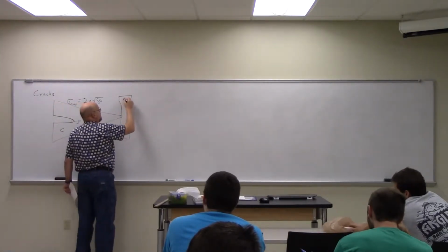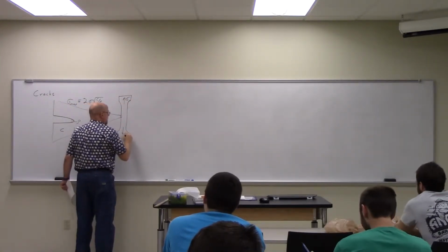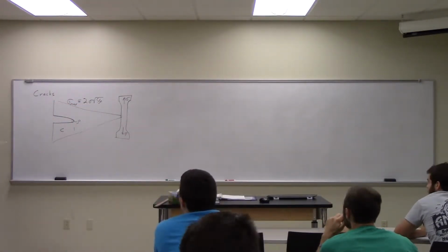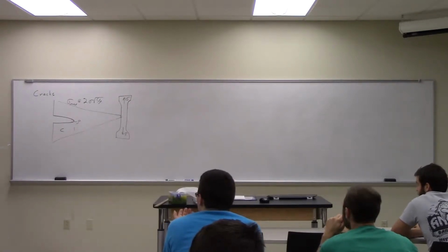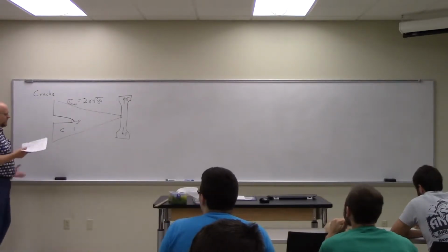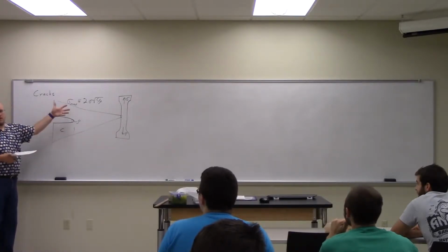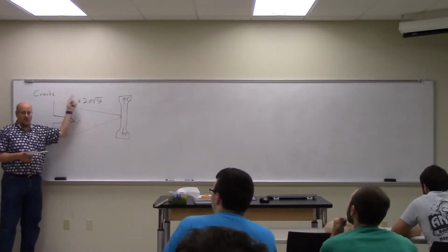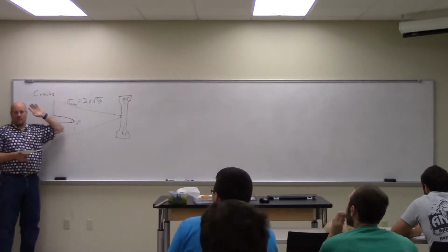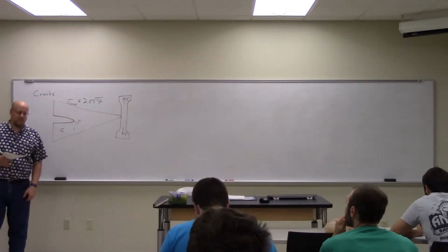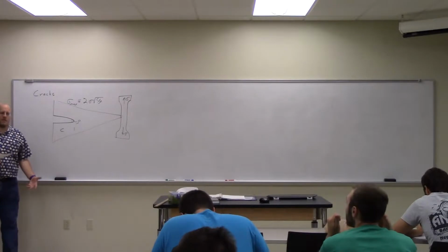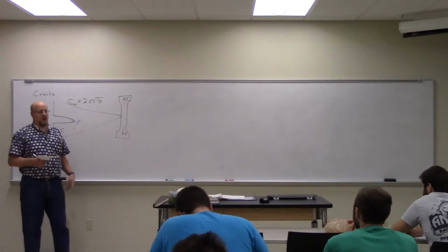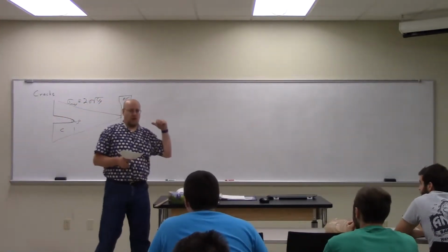So sigma is the stress that's being applied macroscopically to the whole sample. Would it work if we used the S instead of sigma, the S stress? Yeah, see, there you go. It works both ways. But this is what I told you. I'll end up using sigma for engineering stress, even though typically most of the time we're using true stress. So this is actually sigma. But you could also use engineering stress. Because at any instant in time, the difference between them is just the difference in the cross-sectional area. And this is before yield or anything, so there's not been any deformation.